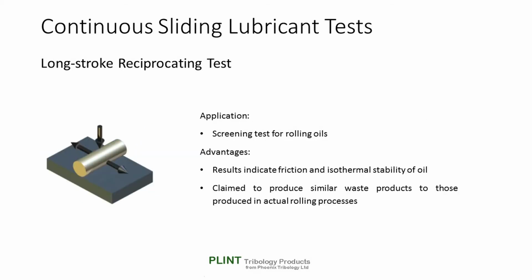A number of researchers have attempted to model rolling processes using a long stroke reciprocating rig and claim to have generated some useful data. They found that because of the low frictional energy input to the contact, tests could be run under almost isothermal conditions.